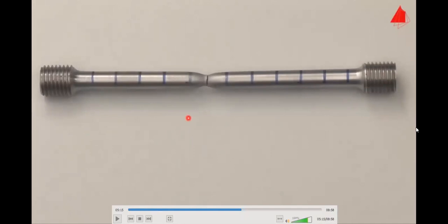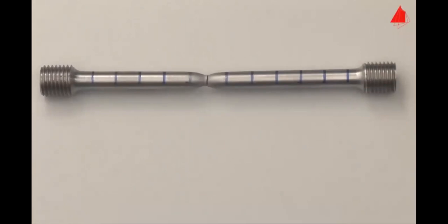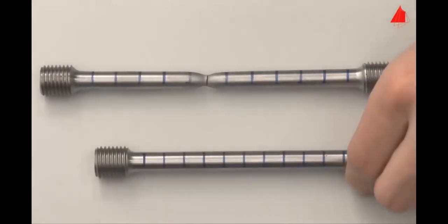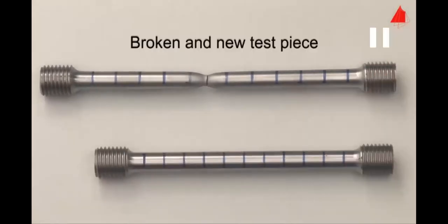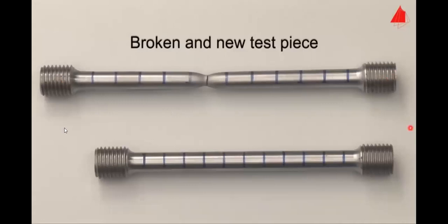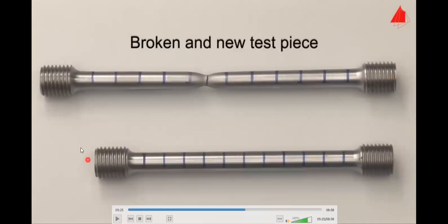With the help of the distance marks, the percentage elongation after fracture can be determined. This is the permanent strain after fracture and amounts to about 30%. So this was the size of our original specimen, and this is the fractured specimen. You can see the elongation, the stretching of that specimen. Almost 10-20 mm has been increased.